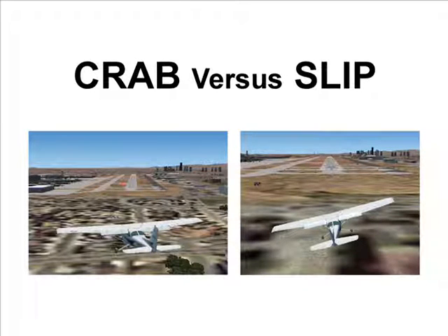Most pilots are taught that there are two methods to accomplish a crosswind landing, either a slip or a crab. This is not precisely correct. What is true is that these two methods each correct crosswind drift. With one exception, optimum crosswind landing technique utilizes both of these methods together. The advantage of one method can then compensate for the disadvantages of the other.